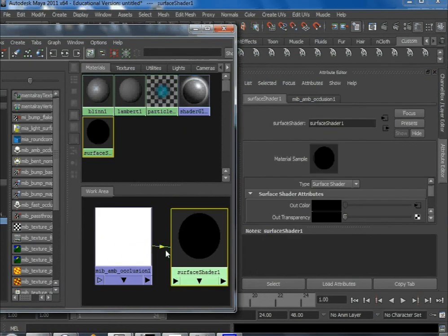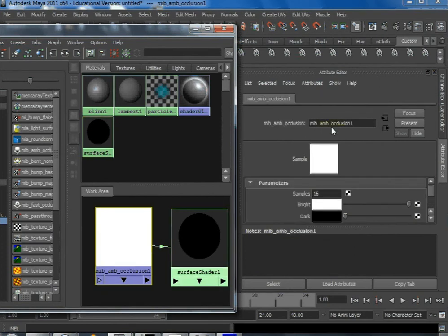So if you click the texture, you can use Control A again to open the property window. It has a value named samples. By default, it's very low, 16, right? So that means it only calculates 16 times per pixel to gather the information.